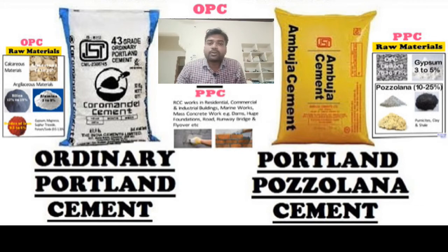But nothing to worry about, both are the same. You will get the same strength, because the strength of the concrete basically depends upon the mix ratio, so there you need to take care of that. And in PPC, Portland pozzolana cement, the curing duration is more compared to OPC, so there you need to take care of that.